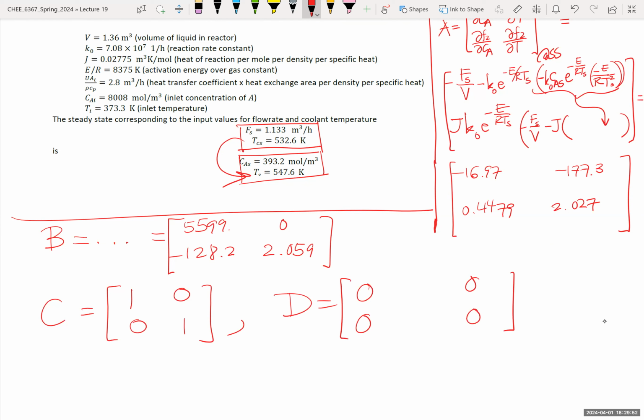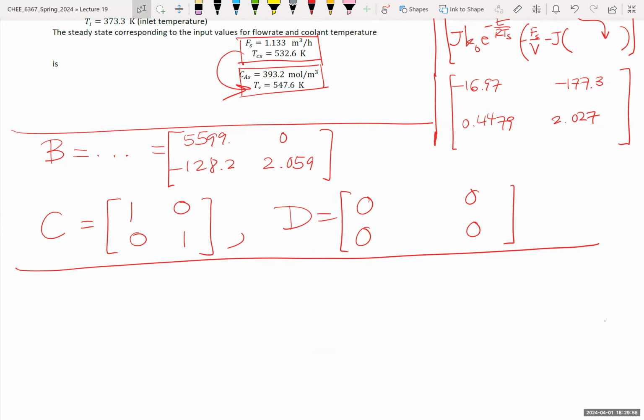Okay, good. And what do we do with this? We can do a number of things. For example, we could design controllers directly in the time domain. A method that we're going to see is the linear quadratic regulator. The linear quadratic regulator, what is this name, first of all? It's called linear because the model is linear. Quadratic, because there is a quadratic objective, a quadratic control objective.